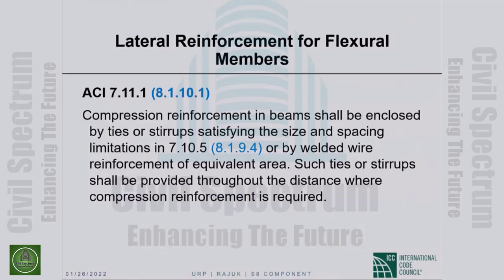So let us say at a beam support section, tension reinforcement at the top, and there is reinforcement. Typically, there is reinforcement at the bottom. If it is seismic construction, we insist on having reinforcement at the bottom, continuous reinforcement, and be that as it may. The bottom reinforcement should be considered as compression reinforcement if it is required to carry compression.